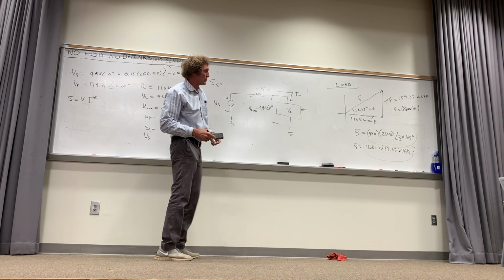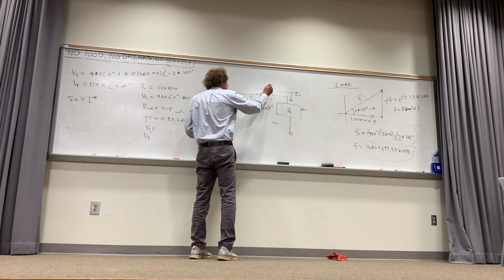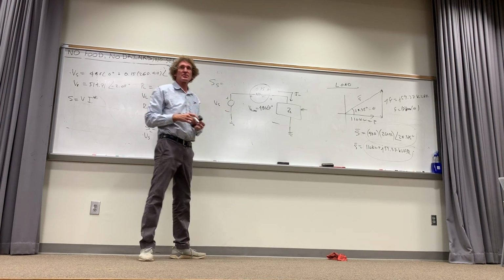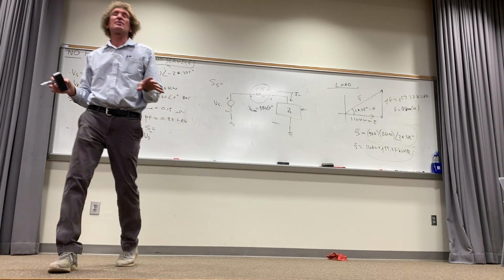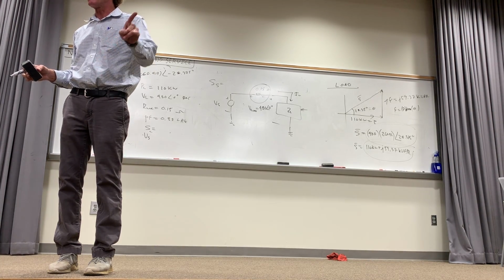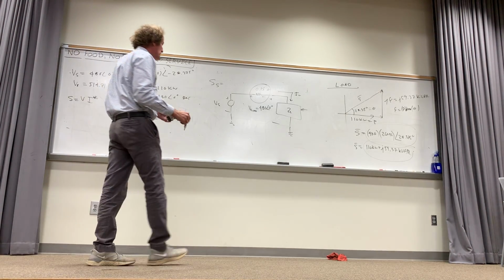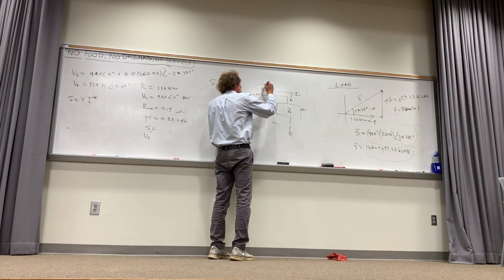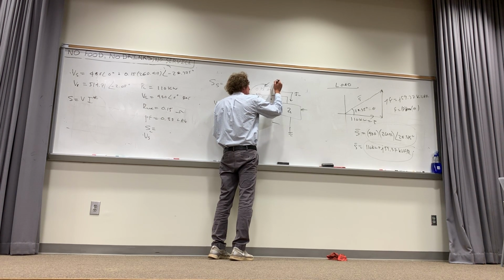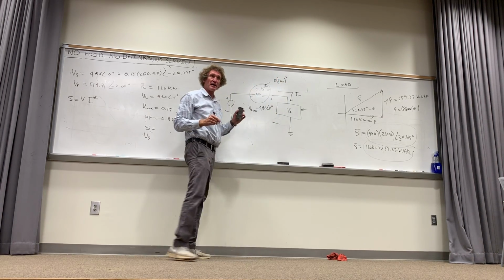And it doesn't matter which form it takes. But this is a resistor. One thing about a resistor, it only dissipates real power. There is no imaginary, right? So I know the power is just going to be on the horizontal axis if you think about it, correct, class? How much power is dissipated by this resistor? What would it be? It would be R times I RMS squared. You all agree with that?